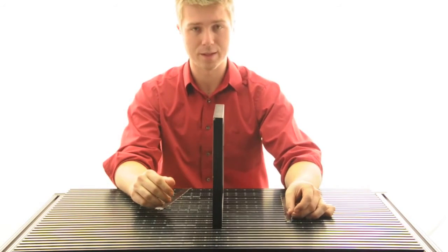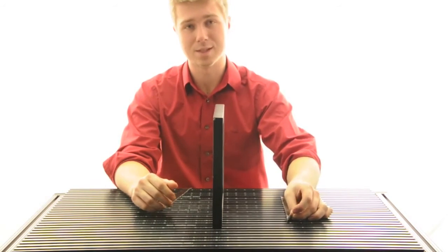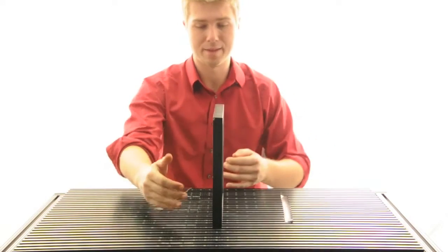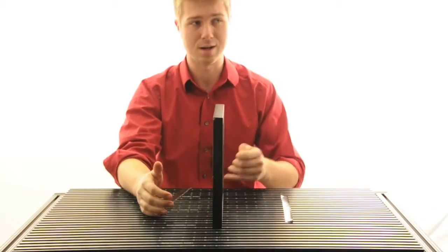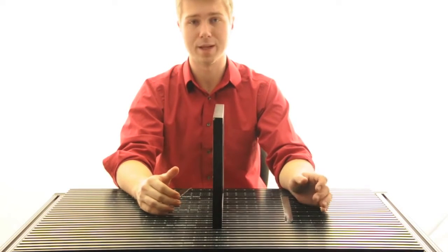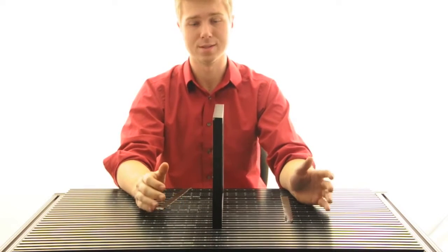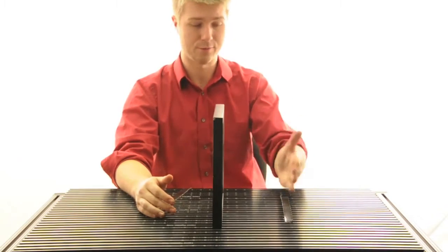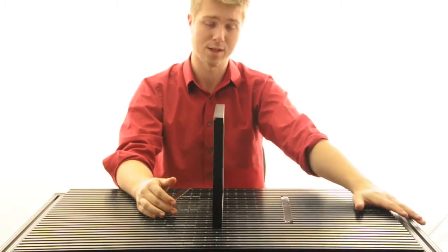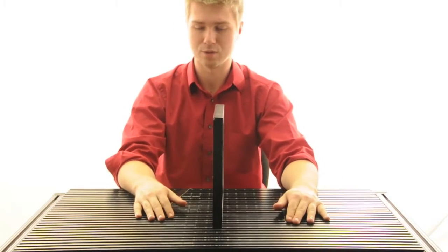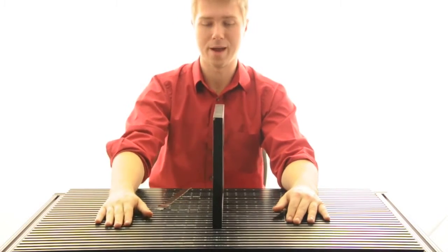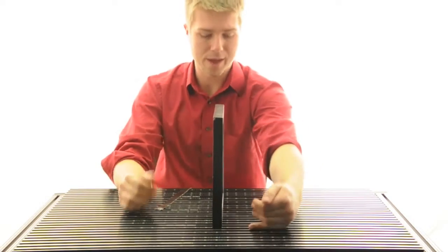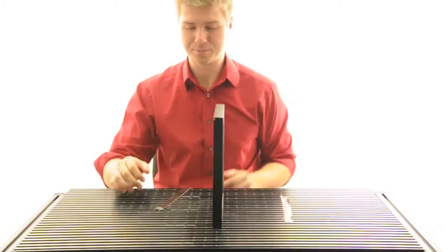So the scanning system obviously scans in stereo because we're using two lenses. That means that the width of our scanning area is only going to be as wide as both of those lenses can see. So that will be narrower in the front of the scanning volume if we have our scanner here, and it's going to be wider in the back, so we make sort of a trapezoid shape. So that width is fixed.